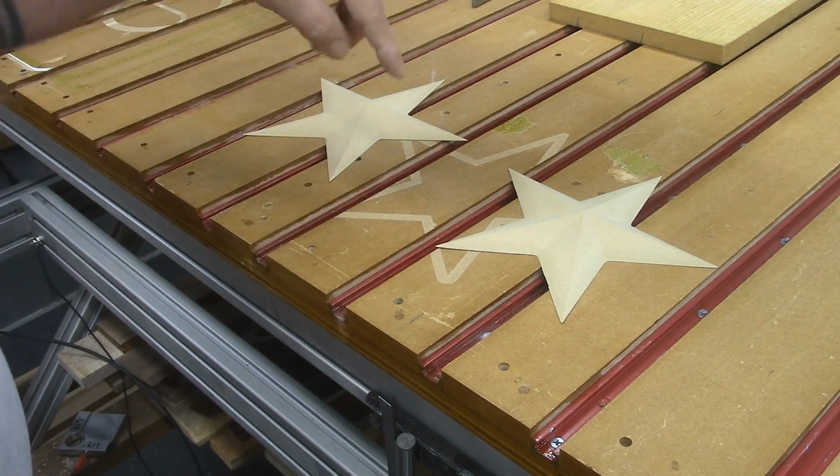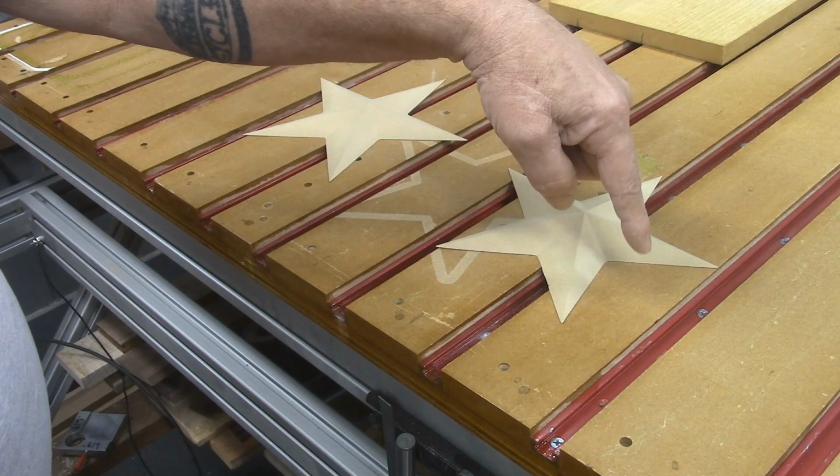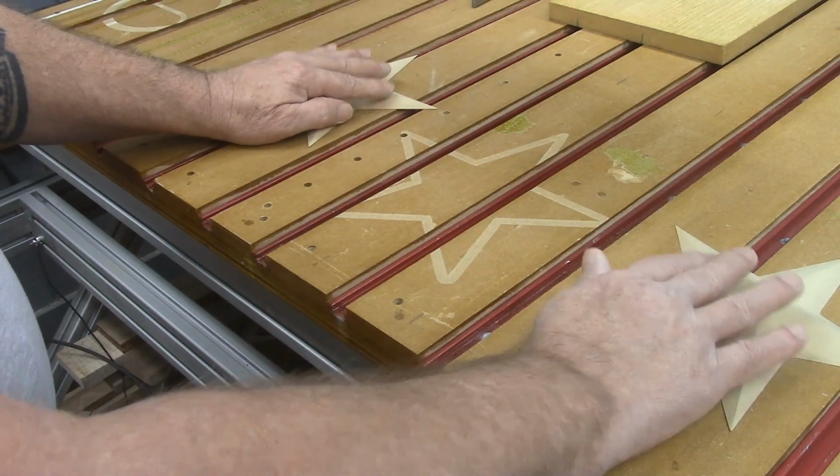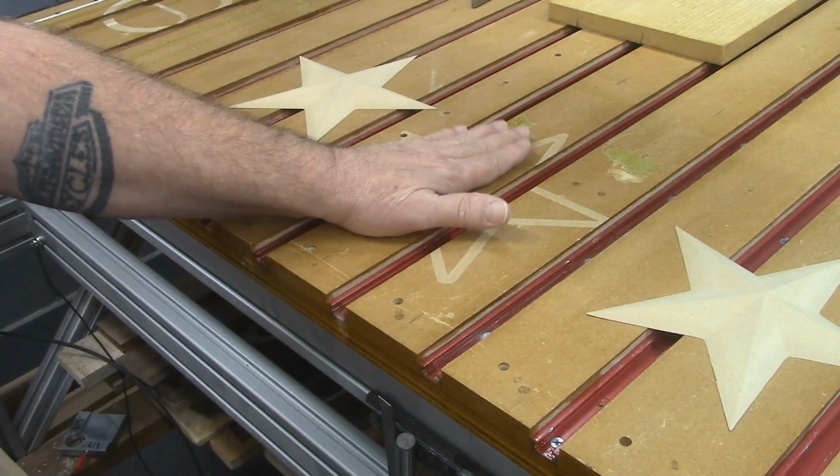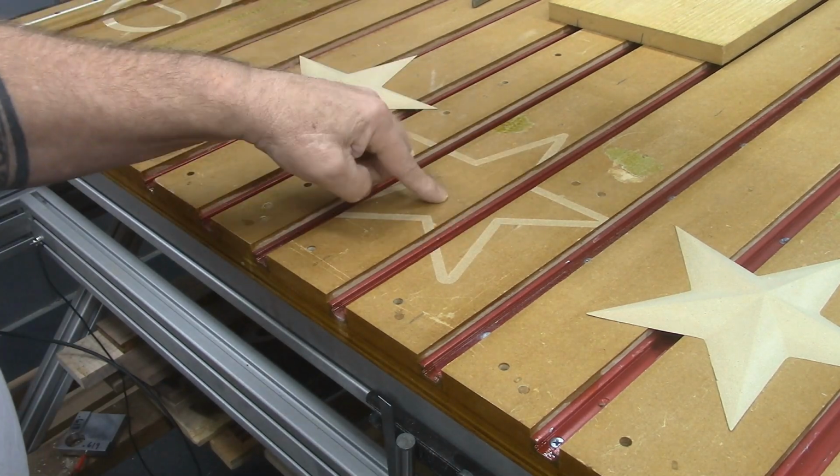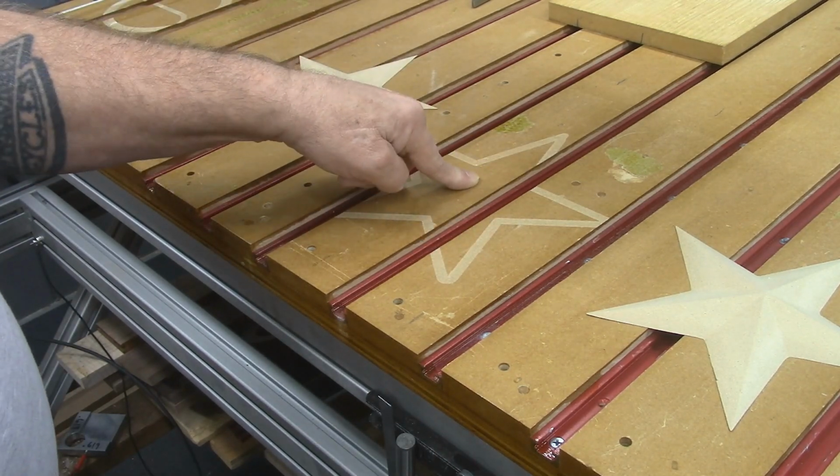If you are cutting all the way through, providing you have your axis calibration set correctly, set your Z0 to the machine bed.